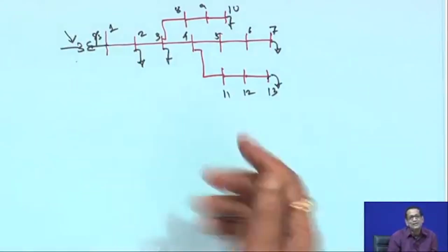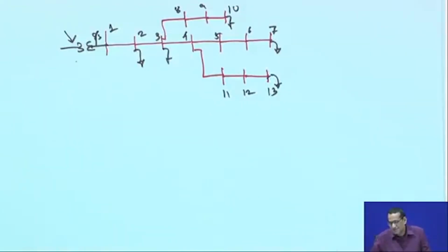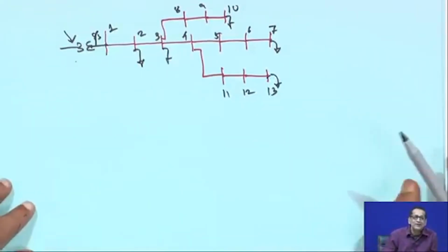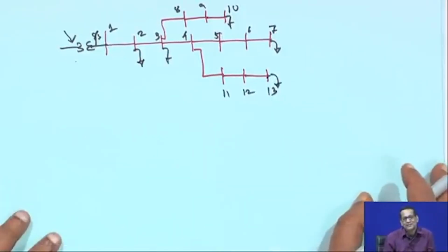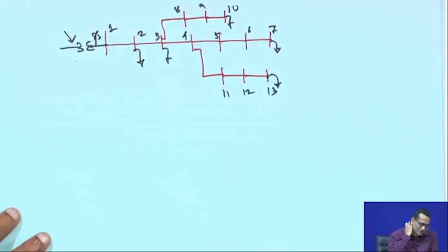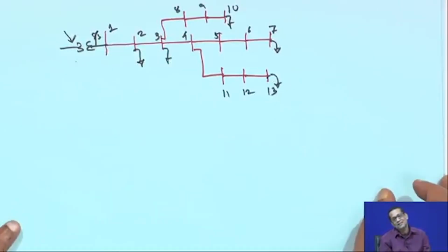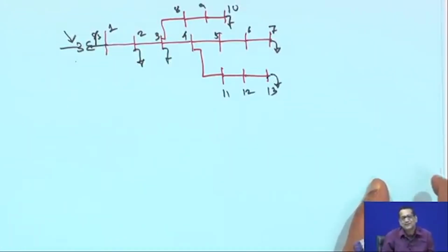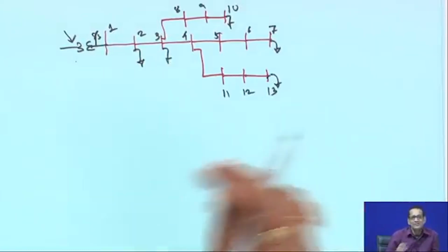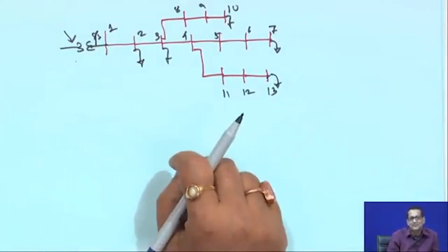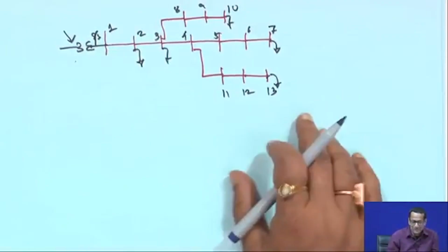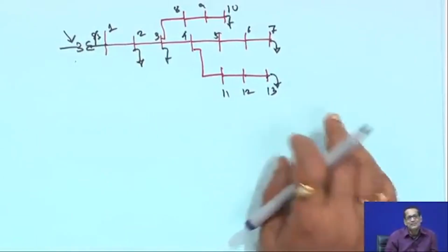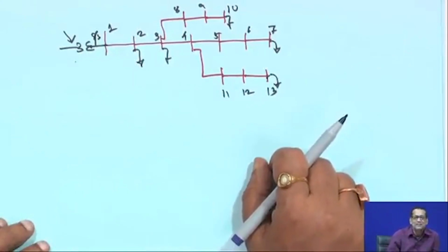Of course, I will tell you about the constant impedance load here. If you have any other questions, you can let me know. Basically, this capacitor is a constant impedance device, because it is connected to the frequency of the system. If it is a 50 hertz or 60 hertz system, that frequency is generally not changing. It is around nominal frequency, sometimes a little less than 50, sometimes a little more than 50. So it is basically a constant impedance type, because the reactance of the shunt capacitor will remain